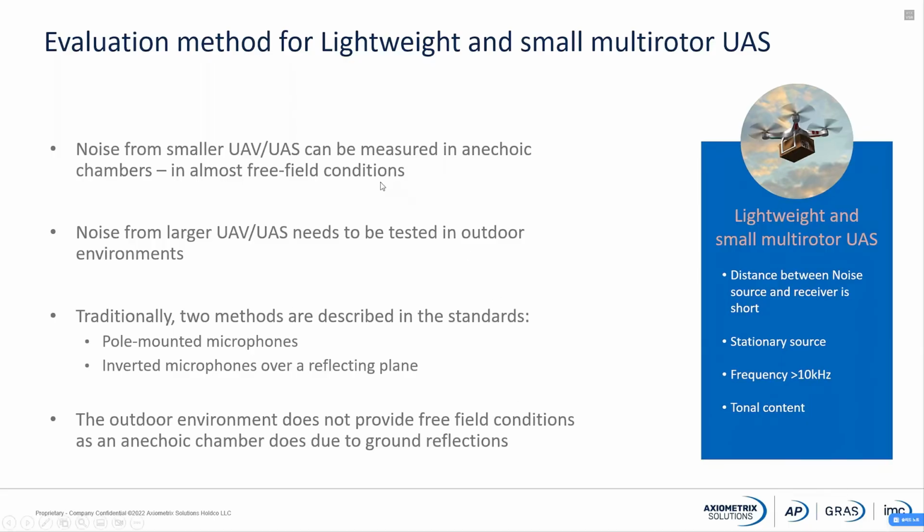There is also another issue. You can say that UAS are very small, and therefore you can test them in an anechoic chamber, which means that you can have almost free field conditions. That is possible for smaller drones and UAVs, but if you have a somewhat larger UAV or UAS, they need to be tested in outdoor environments.